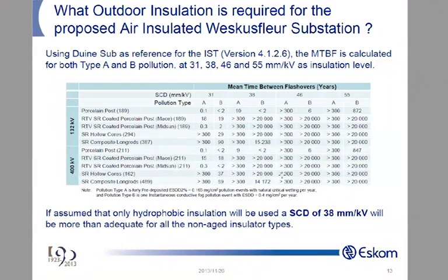And by the way, bring in life cycle costing. Because now you need to convince bean counters to go for something which is maybe a little bit more expensive. But you need to look at life cycle costing to show them that the selection which you are actually proposing is going to long-term be the most cost-effective. And don't forget the whole scenario of getting rid of insulators at the end. Because to get rid of insulators at the end is a cost, which a lot of people tend to ignore. And between the different materials, getting rid of these things can be quite costly.